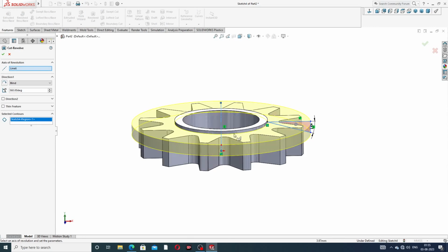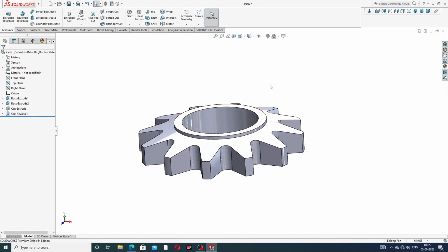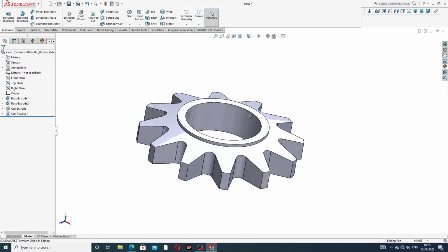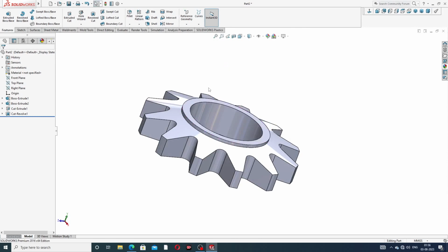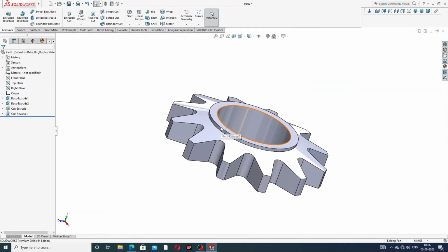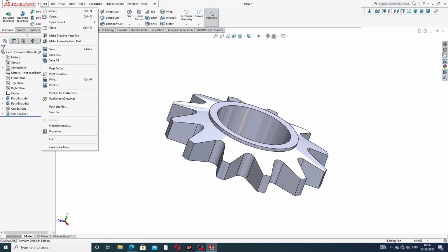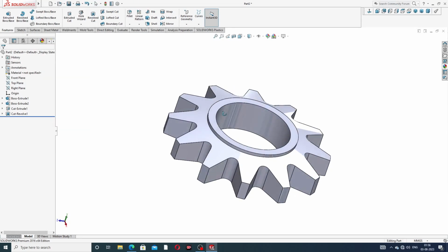Okay, revolve cut is applied here, and this inclination, okay, this 15 degree is cut here. Okay, all is perfect. And next use this thread, and thread is very useful, and easily use a first part drawn here, and this thread is perfect, and select, okay, this thread is perfect, and select this part, okay, and insert.